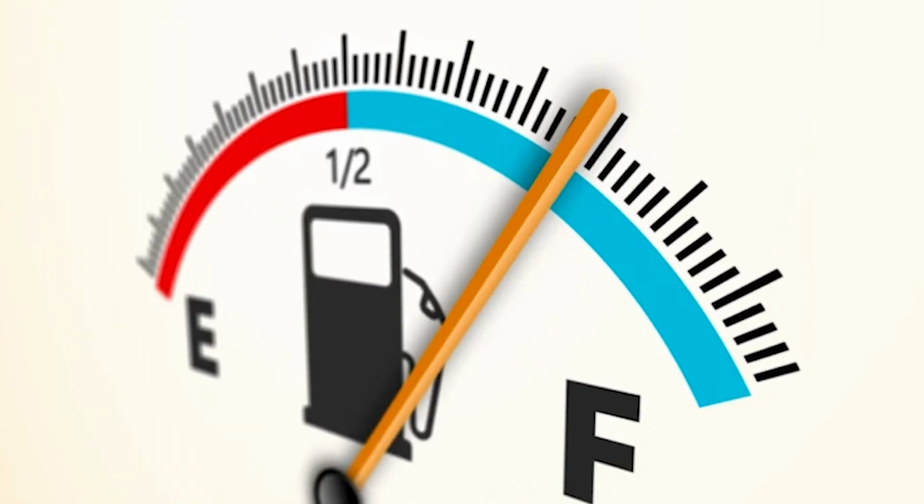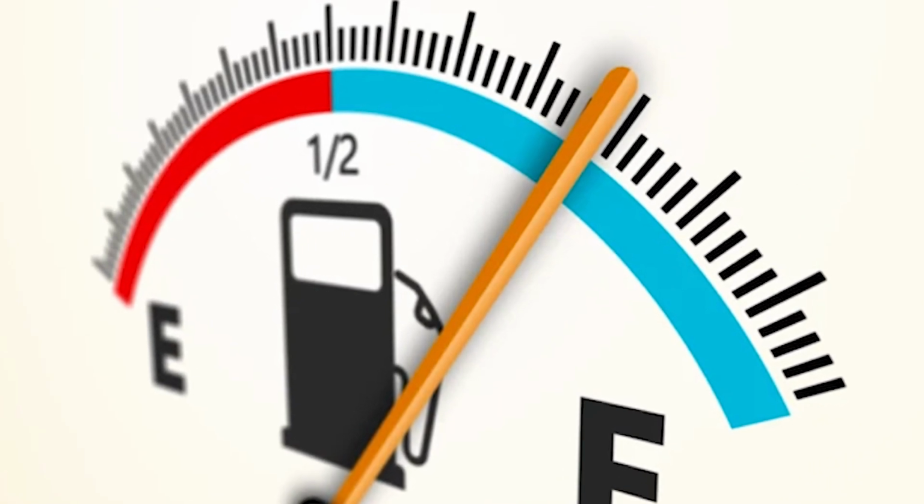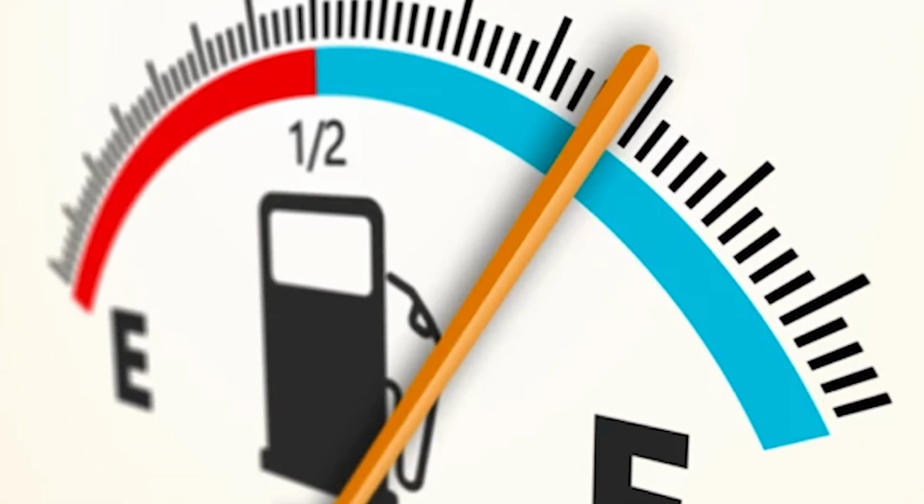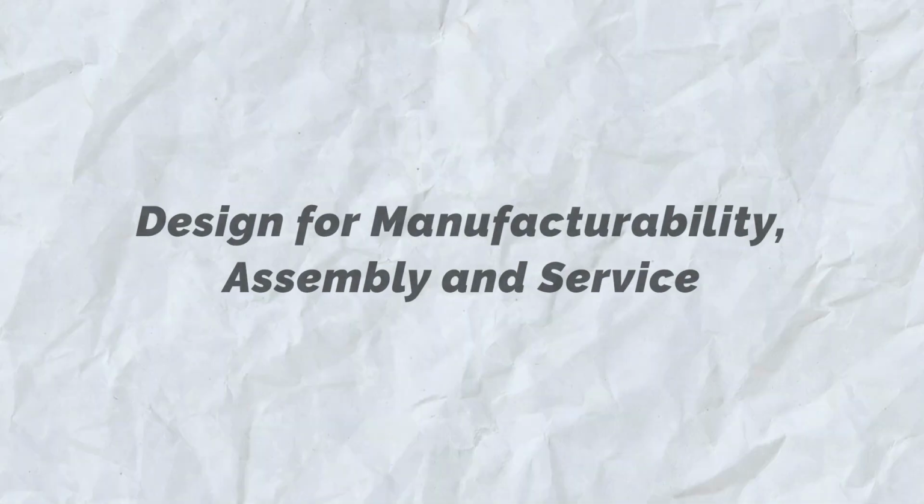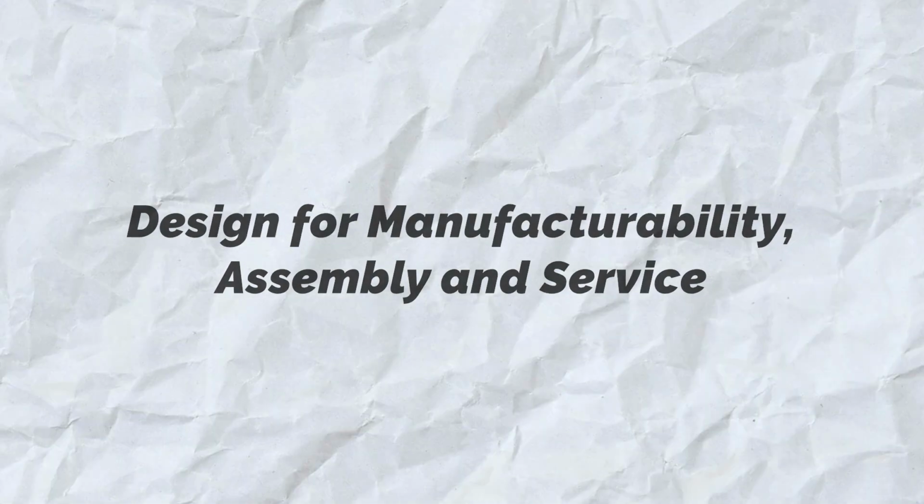When we talk about design failure mode and effects analysis, we are talking about a case where we are making this particular car. What can be the possible design failures which can come in the car, and how do we anticipate them earlier? Maybe in previous experience we must have seen failures which may have happened in the previous design. So what needs to be done with respect to that? For example, it could be as simple as fuel efficiency. Now in India, fuel efficiency is given a lot of importance. So what needs to be taken care of, and what are the possible reasons which can impact the fuel efficiency, can be a failure mode.